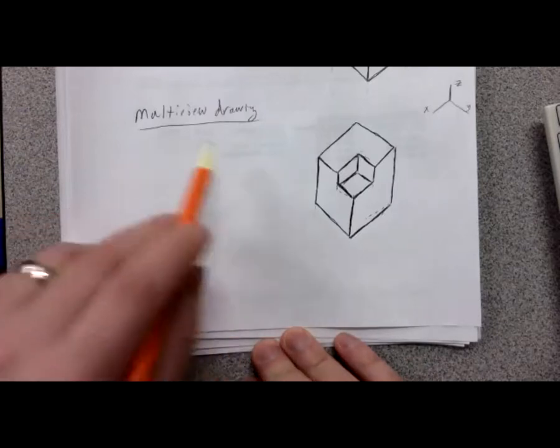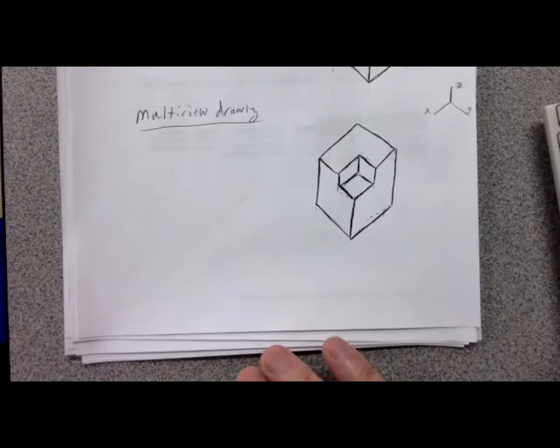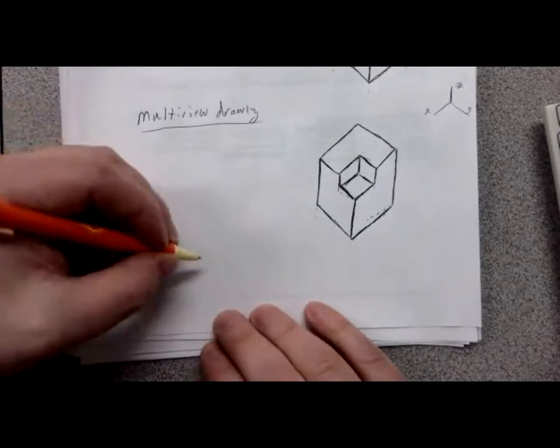Right? Just draw them all over here, front, top, and right. Just draw them, done. None, never. I will count that wrong. Not a lot of points, but I will count it wrong. Your projections should always line up because they work together. No one projection fully defines the part. They should all work together. So make sure they line up. And so I'll show you what I mean there.